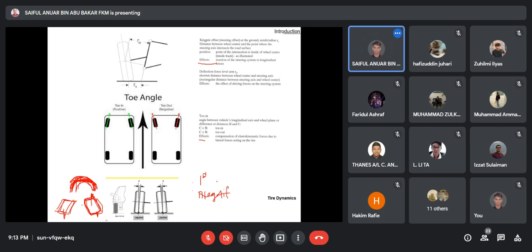And that is for front camber adjustment. For the rear camber adjustment, usually we don't adjust the rear axle. If you want to increase the camber angle on the rear axle to increase the track width, you can still do that, but you need to change your lower arm to an adjustable lower arm. That is an aftermarket part, and for OEM it is usually fixed. The camber angle will be fixed no matter what.